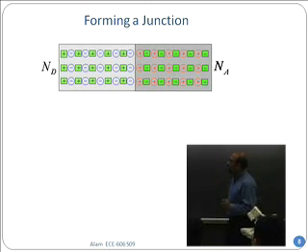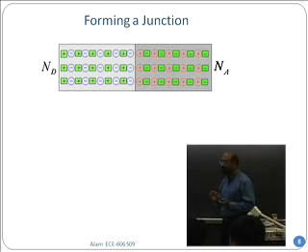In the picture above, what I have shown is Nd is donor, and the plus squares are donor atoms fixed in space, because donor atoms cannot go around. And it has given away an electron. That electron sitting next to it is in a blue circle with a negative sign. That's the electron. So every donor has given away one electron, and therefore you can see every green square is matched with a blue circle on the left hand side, on the donor side.